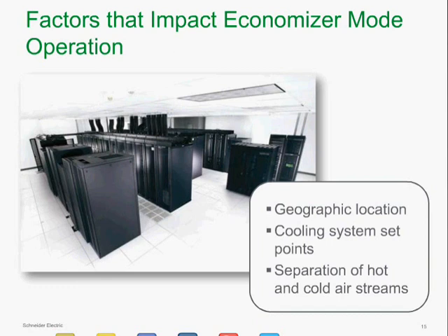In the past, I think we've all been in facilities that are like refrigerated meat lockers. We've seen data center set points back in the mid-60s, and I'm talking Fahrenheit temperature there, not a time period. Nowadays, we're seeing most engineers designing facilities to 75-degree Fahrenheit set points for supply air to the inlet of the server.